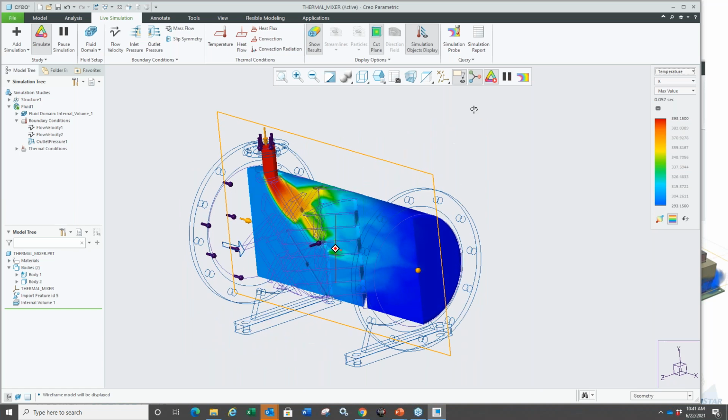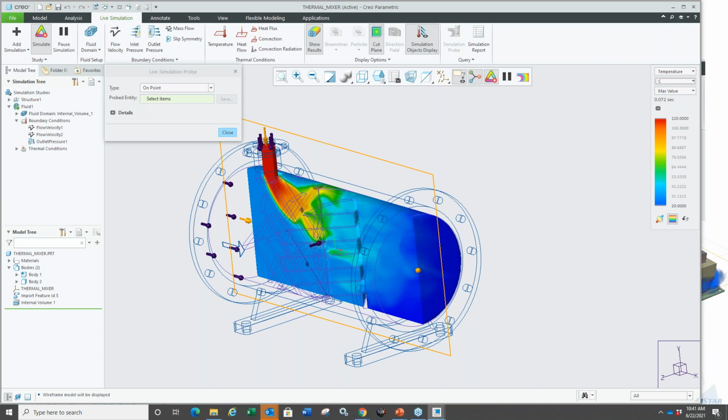I'm able to add a new probe, for example. I could say, let's add a probe to this. Maybe we'll set the temperature to the unit system that I prefer right in here, because a probe is essentially created based off of that. I'm going to do a probe in here, and it gives me the 21 degree, whatever. It's still settling in, still reaching that steady state as we speak. And I'm able to click on this graph, and it'll show me the change over time.